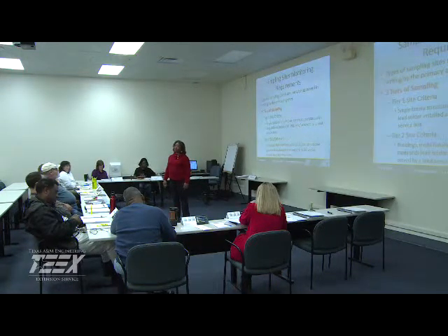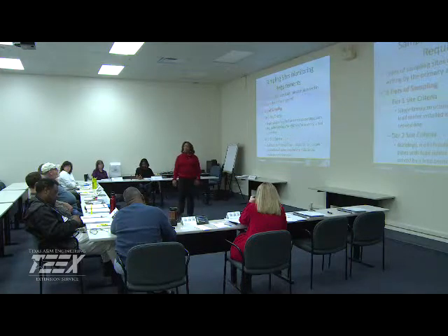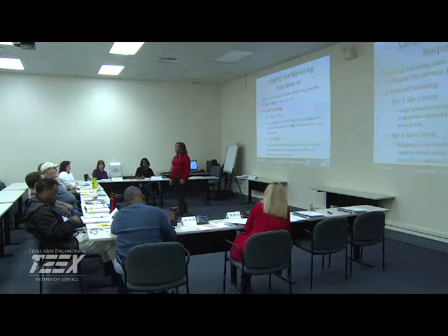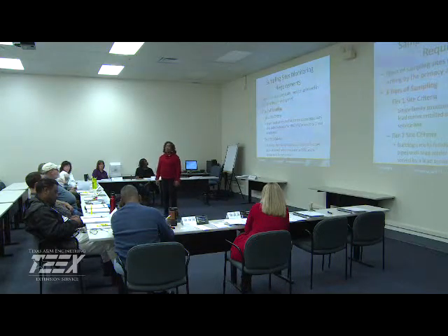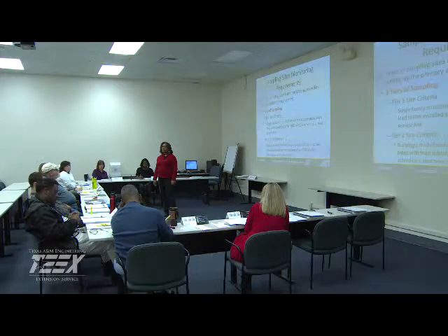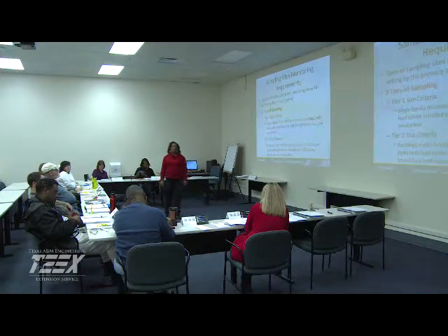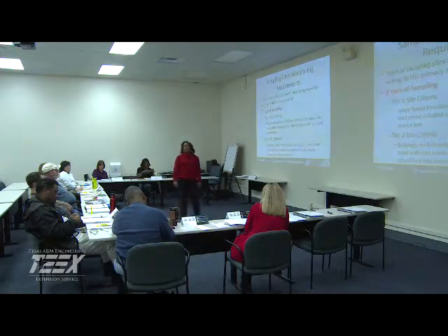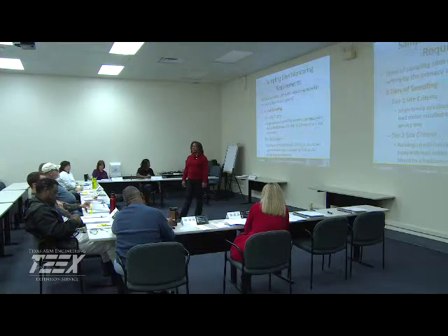There is still the minimum monitoring now, and I think you go to once every 6 or 9 years, up to 9 years for some monitors. But you still have to document that you don't have any sources of lead and copper in your distribution or source water. We don't have it in our source water in Delaware, but I still get a blue-green stain.